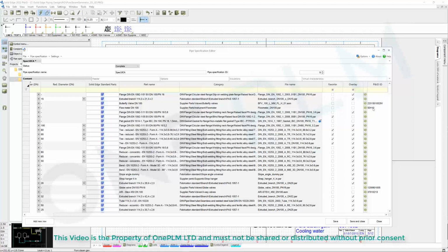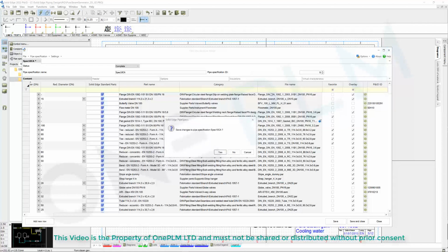This number here, the component ID, allows us to link these parts together. So if I've got a butterfly valve and I apply this to the P&ID, that means my software should automatically know that is that part. If I've got that in the 3D, I can assign to that and it will go, yep, good, green tick, etc. So let's jump back into the P&ID.